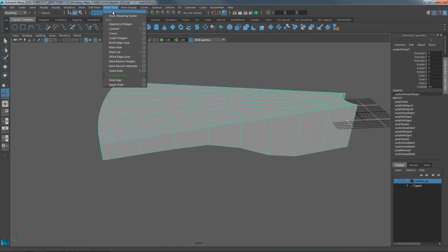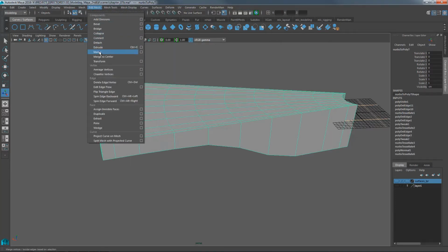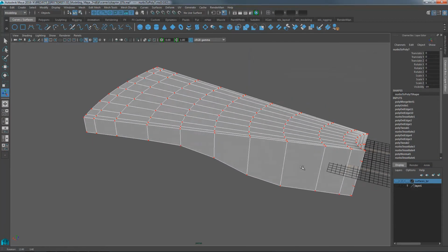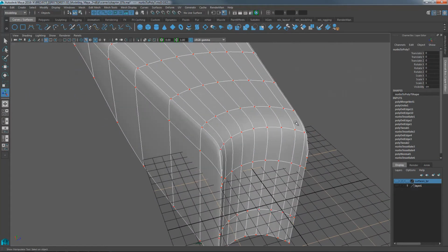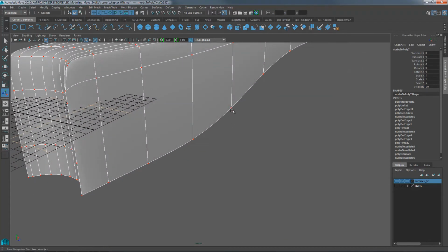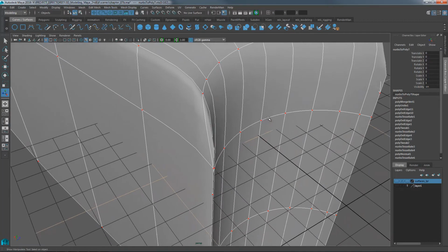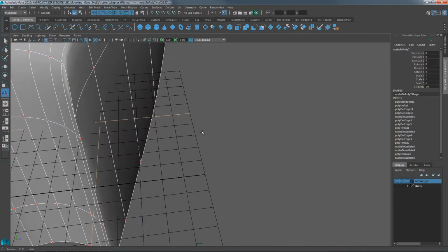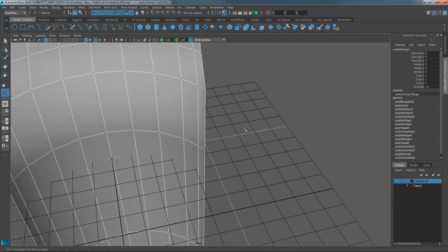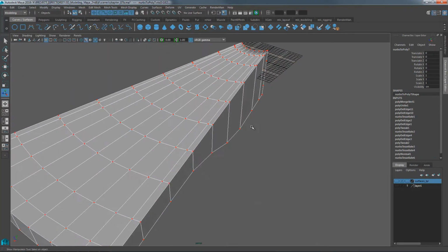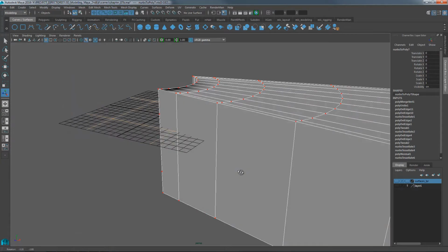Then merge any remaining vertices. Be sure to do that with a very low tolerance. So that should capture everything that sits on top of each other. Tap number 3 just to confirm that things did come together. And it looks like we're good. We might have just a small problem on the corners, but it's very, very small, it's really nothing. Okay, not a big deal because we're going to attach to that cylinder.